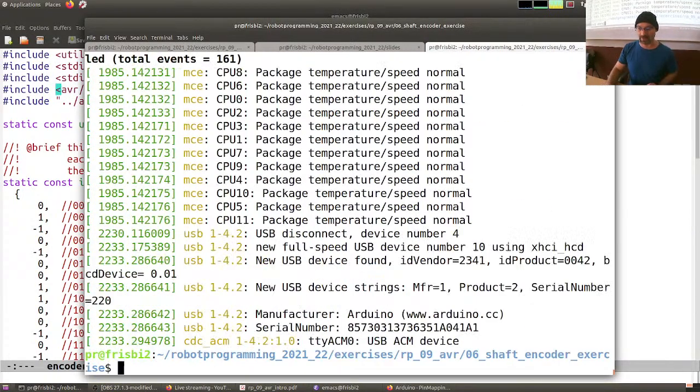The message is a program that prints the kernel errors, or the kernel notifications. Once you do something on your devices, you're reading on the message what is going on, and it says, "Oh, I found a fantastic thingy. Oh, you disconnected. It was me before. I found the device. I queried the device. I discovered what it is. I also have a serial number." Of course, this is a fake board, but it's perfect. And it's located in ttyACM0. That tells me where I can run the things.